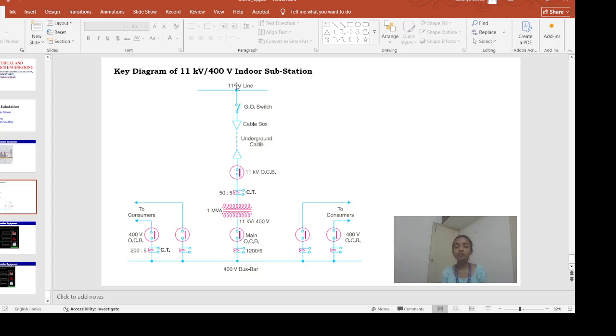Okay, so here if you are using a three-phase supply, and this gang operating switch, for each phase we are using one switch. When many switches are operating simultaneously, we call it a gang operating switch, or these are nothing but the isolator. So obviously this isolator will disconnect the faulty part of your circuit from the main supply if there is some fault.